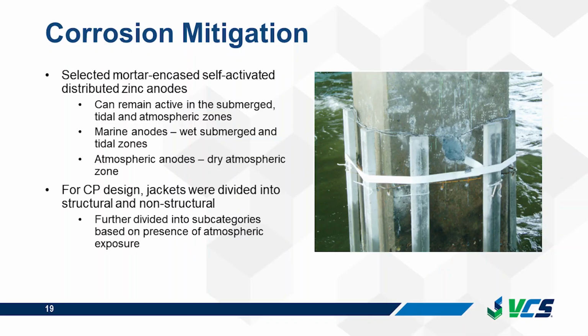And this resulted in a combination of exposures for different piles. There were piles that were in submerged and tidal zones only, while other piles had areas that were submerged, tidal, and exposed to the atmosphere. So because of that, we selected mortar-encased, self-activated, distributed zinc anodes. And this is an example on the right here.